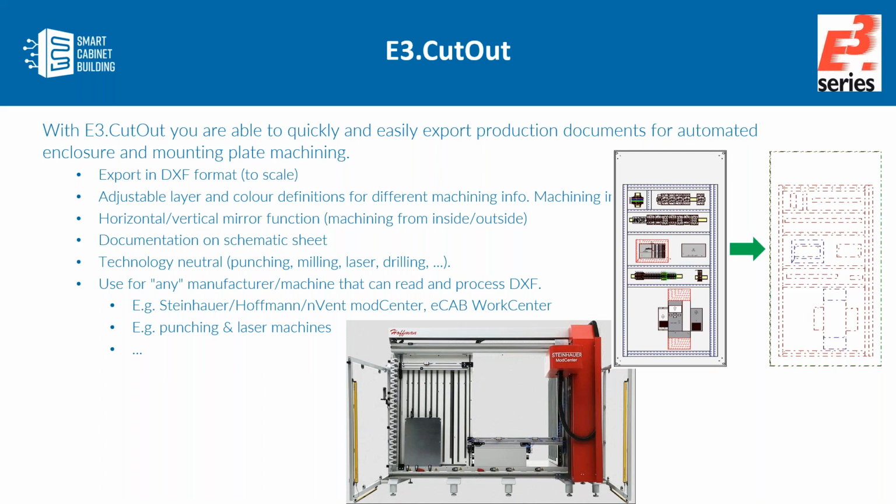The most typical machines have an interface to import those cutout drawings via DXF, and that's for us a neutral format. Neutral means it is independent of the manufacturer of the machine as well as the technology of the machine. So this works on punching machines as well as on milling or laser or drilling or something else if you do it by hand.